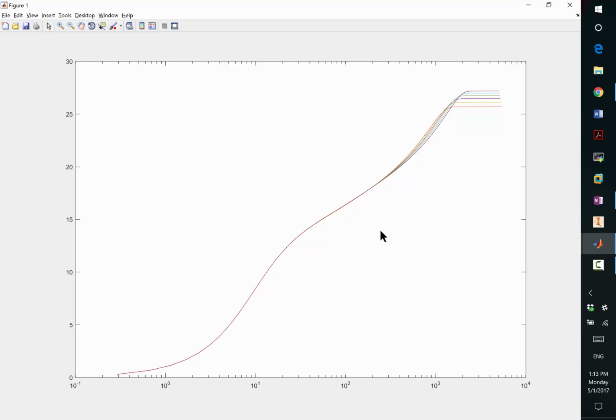So if you divide, the u star is directly proportional to, you're right. So the top one is the last station. The bottom one is the first station. This is because the free stream, or UE, is the same for all these stations, right? So if you didn't normalize by the friction velocity, the flat region of the profile is the same. That means the top one has a lower friction velocity, and friction velocity is proportional to the square root of tau. So the top profile is going to have a lower tau. As you move along the flat plate, the skin friction decreases as the boundary layer thickens. So the top profile is at the highest Re_theta, or the latest position in the boundary layer.